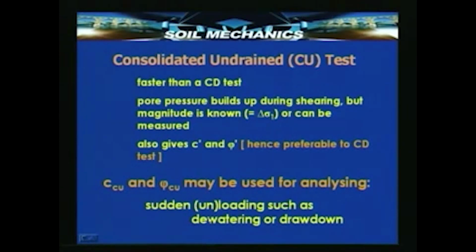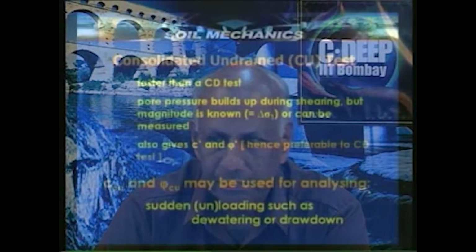This test is good for situations where an embankment, for example, has spent a little bit of its life and now it is undergoing a sudden unloading. In such a case, C_CU or phi_CU will apply. Examples are dewatering and sudden drawdown.